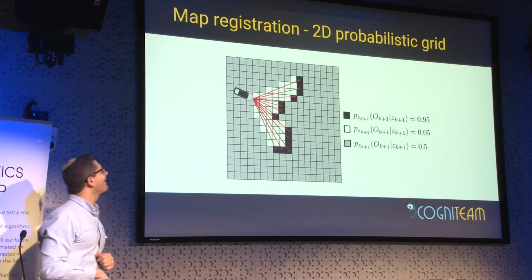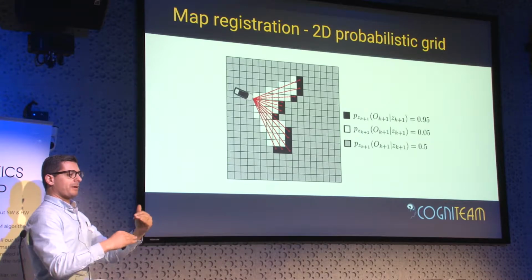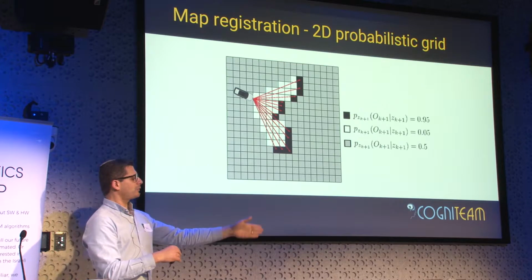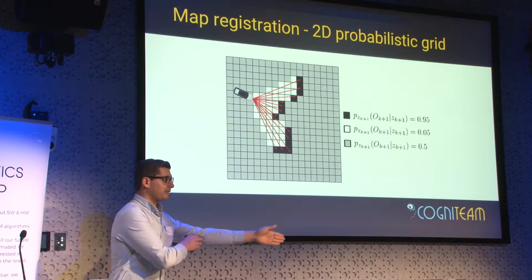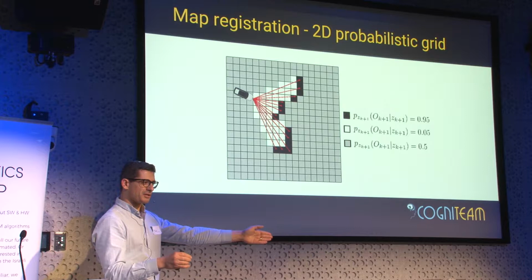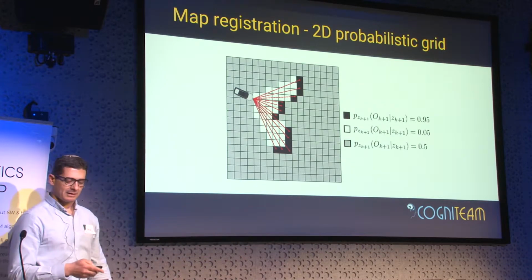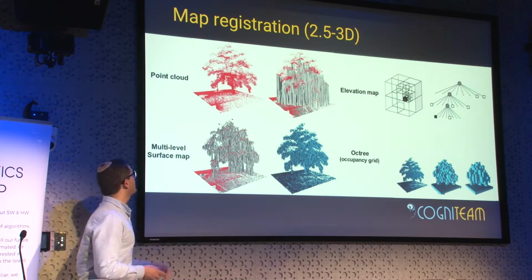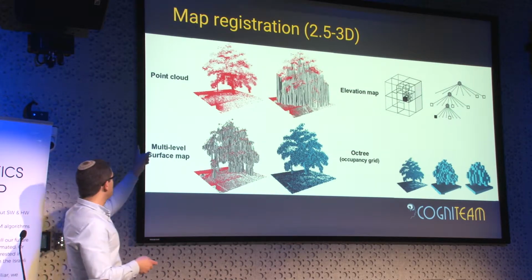We present the map based on the occupation probability, because if I see this place and it is always free, then a person moves and now I see it's occupied, I will not put it as occupied. We want a robust map, not a map that changes because of small changes. That's why we collect the data as probability data. Another way to save maps is a point cloud.